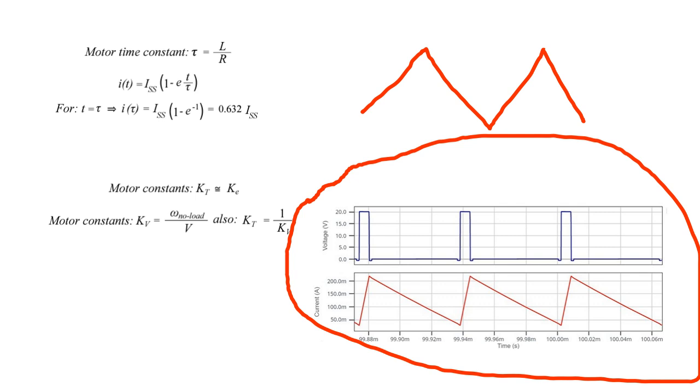Some motor types are very capable of regenerative braking because they have high energy storage capability. Their inductance is very high, so they store energy. Some motors' inductance value is very small, so they cannot store any energy. If you want a special motor type for some application, you must check the parameters of the motor.